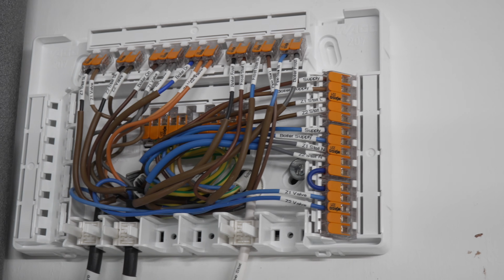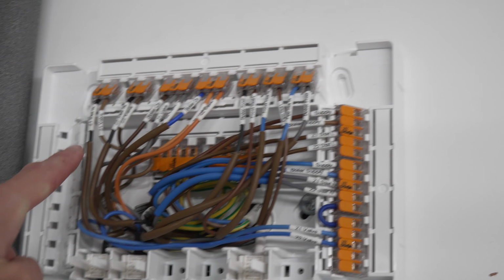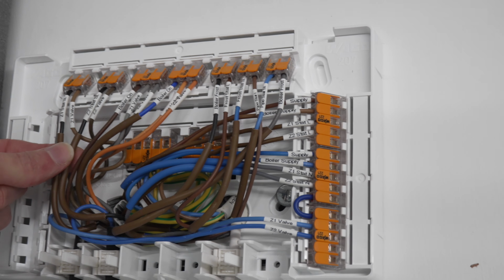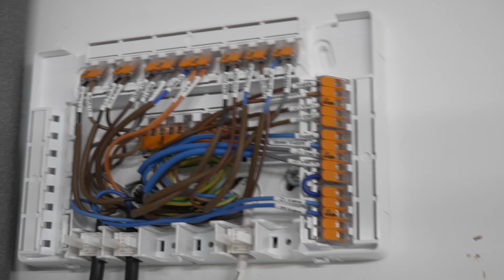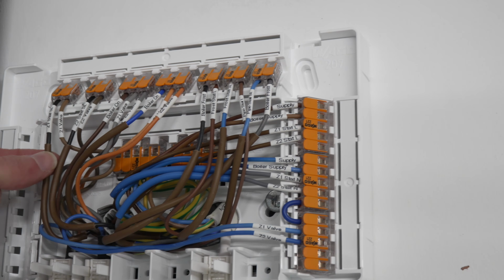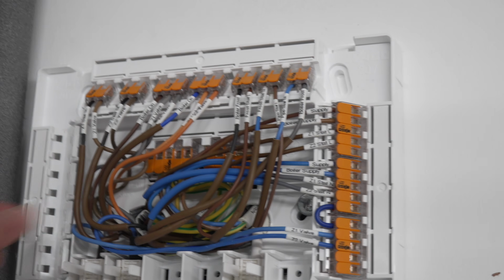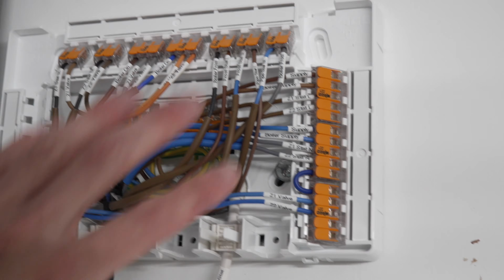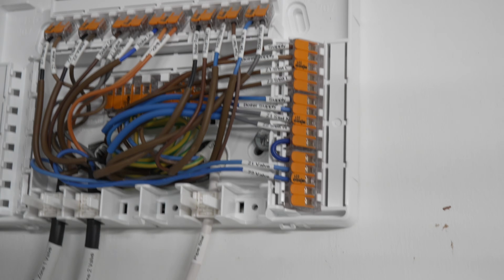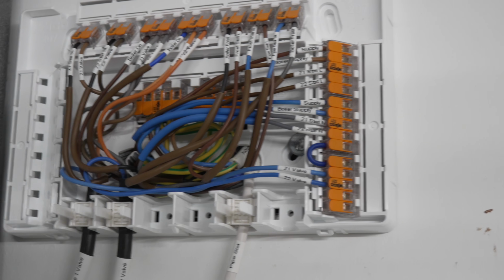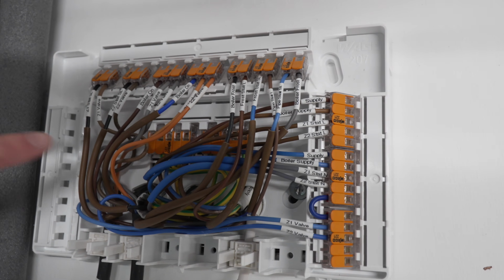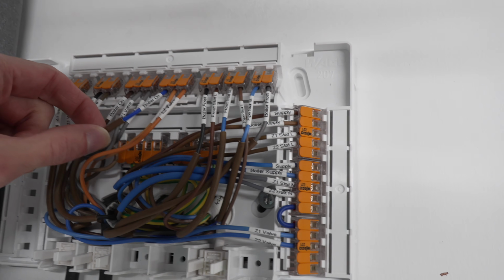So with this setup here, essentially all we really need to do is disconnect the switch lines from each thermostat, get them out of the way, disconnect all the other thermostat wiring as well, and connect the switch lines out of the Wiser hub into the terminals that the old thermostats used to connect into. But given I explained earlier how the valves work, I'll do a quick explanation about how this all roughly works, and it might help you if your setup's not as labelled as this, to help you identify which wires are your thermostats. So up at the top here, we can see we have these two wires labelled boiler on.